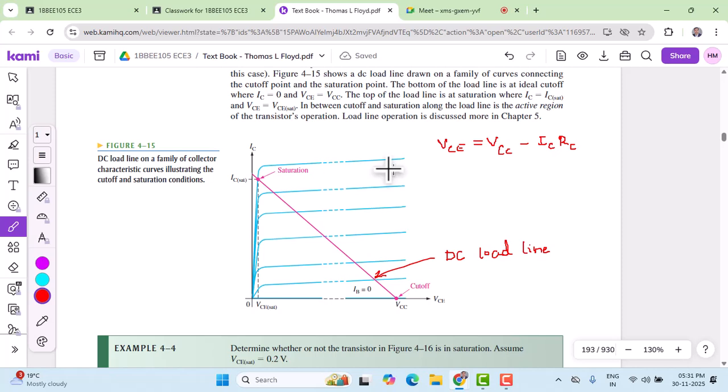Okay, so let's try to find out the base current. This also can be obtained by applying KVL to the base emitter circuit. This is the base emitter loop. If we apply a KVL for this group, minus VBB plus the current flowing through this, let me take it as IB. Now I need to take a drop across RB, which is IB times RB, and here we have a voltage which we should not forget.